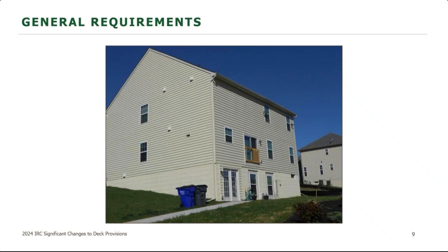If the stairs are moved to the other side but run along the building to the right, going to the right on the screen, they could run right into that last window, which would then trigger that window to have safety glazing because it's now along a stair or walking surface. So you can see how a deck may require alterations to make sure that the existing house is not less compliant with the code under which it was built.